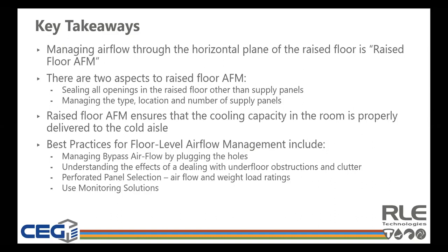And then we went into 6 best practices for floor level airflow management and listed 4 of them here. Managing the bypass airflow by plugging the holes. That's consistent from the rack into the floor, and that's why we talked about those 2 aspects of the 4 R's usually going hand in hand, or done one right after the other.